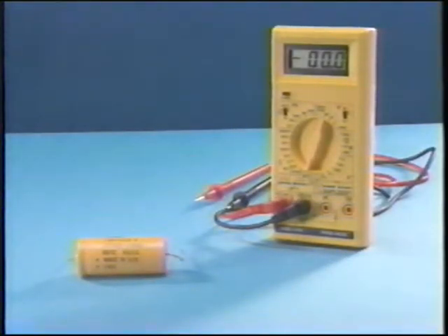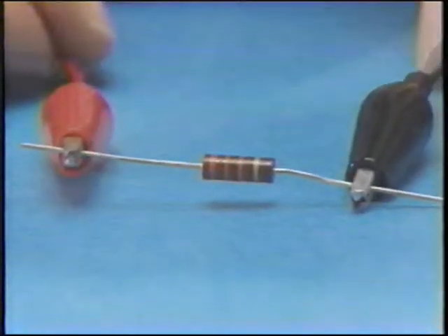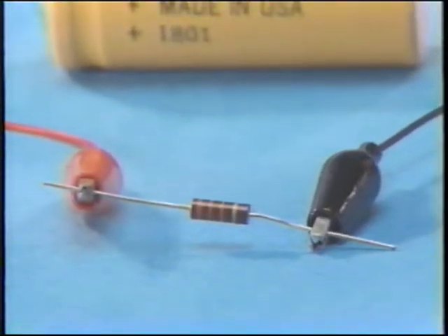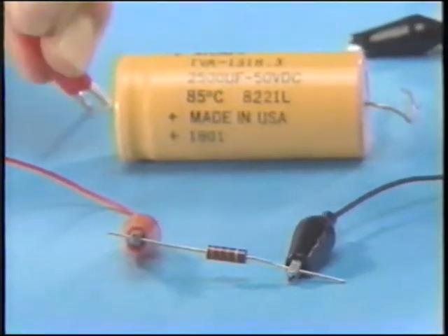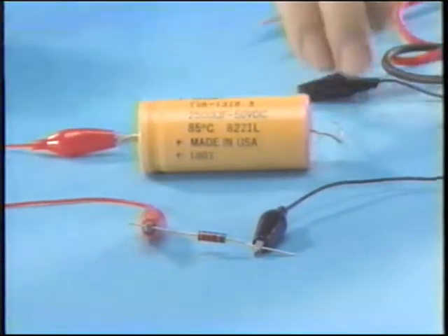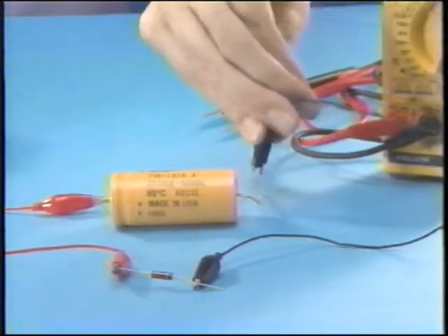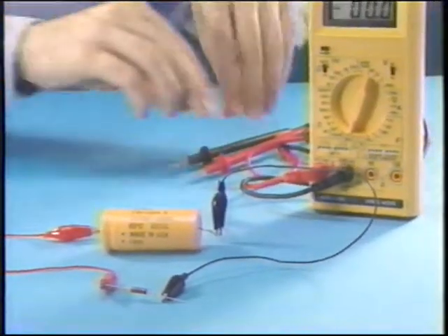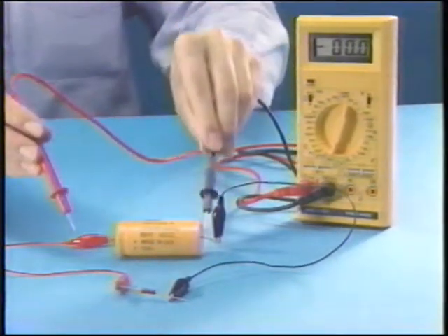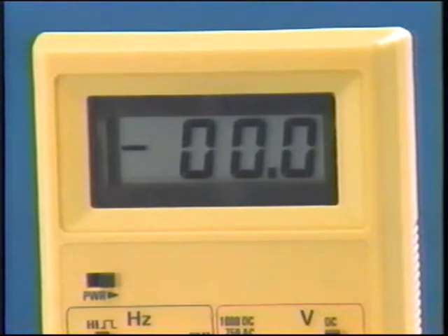Imagine that you find an unidentified capacitor. The best thing to do in order to be safe is to check to see if it's charged with your voltmeter. This procedure assumes that your voltmeter is capable of reading the highest voltage that could exist across the cap. To discharge a cap, use insulated alligator clip leads to connect a high-value resistor across the cap. This will safely discharge it. A cap that is discharged should read 0 volts across it.